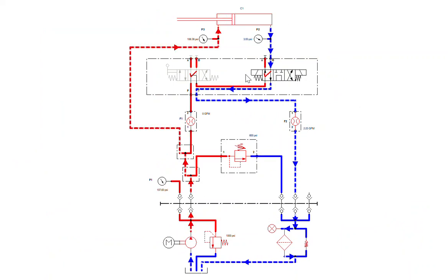You got to be quick to spot it, but watch what's happening to the flow F1 and F2 while this is extending. More than pump flow is going into the cylinder because it's the pump flow coming in here, but it's augmented by the flow coming out of the retract chamber, which regenerates and joins the pump flow to go into the extend chamber, and there's no flow back to tank.